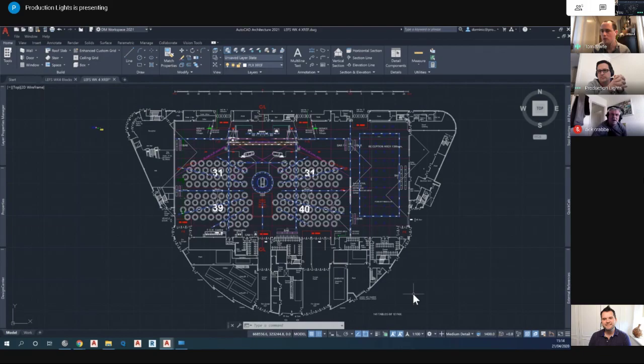Absolutely, it would compare the two drawings as long as they've got the same origin points. Totally from memory, I can't remember, Dom, if you agree, but I believe nothing's changed is grey, change from one drawing is green, change from another drawing is red, and in addition, it will produce a revision cloud around the area, which is terribly, terribly handy.